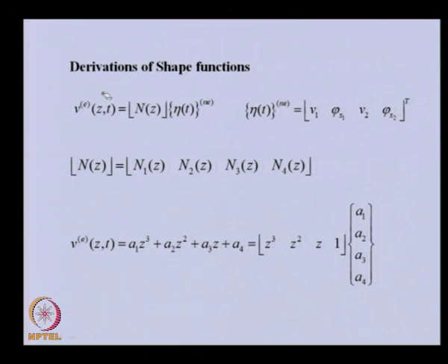As we have chosen the shape function as an approximation, and we have the nodal displacements in the element as these 4, because there is a 4 degree of freedom element with 2 nodes, we expect there will be 4 shape functions. As we have seen in the previous condition, a cubic polynomial is sufficient to represent the shape function for this particular problem.